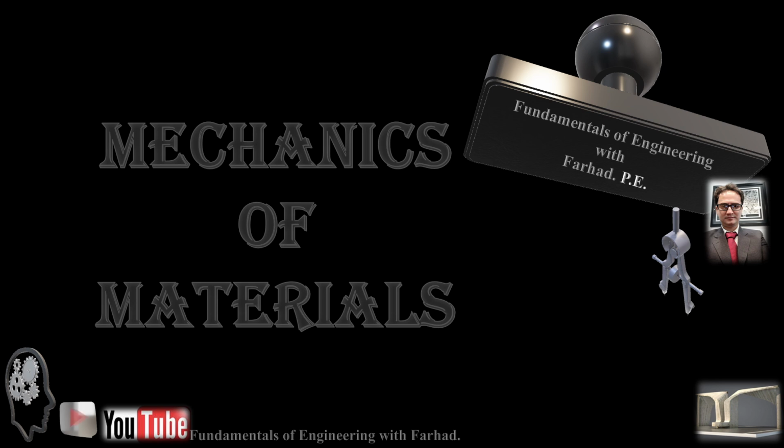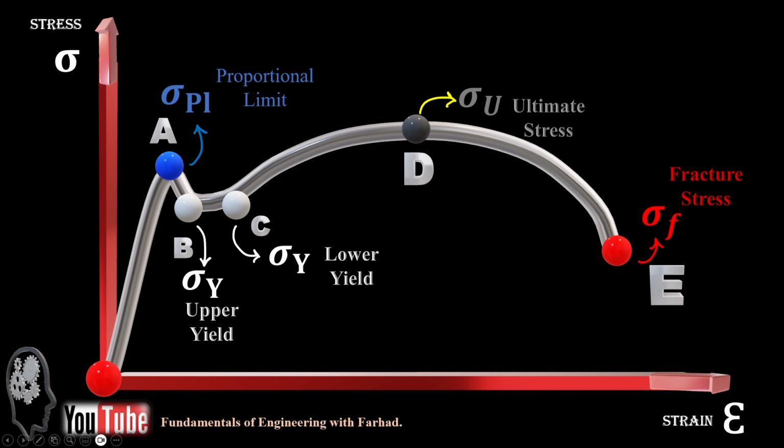Today we review an interesting concept in mechanical properties of materials relating to a stress and strain diagram. If you look at a stress and strain diagram, for example, of a steel or such material, you can easily see there is a linear part that moves to point A, which we call sigma proportional. And the reason we call that proportional is up to point A, there is a linear relation between stress